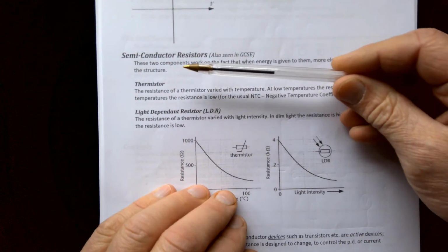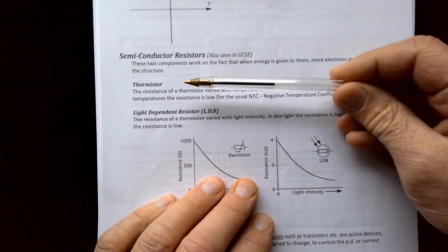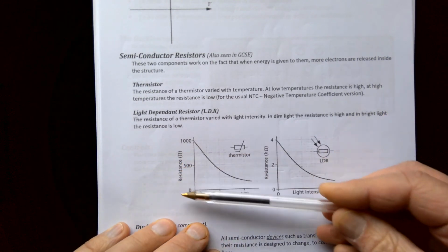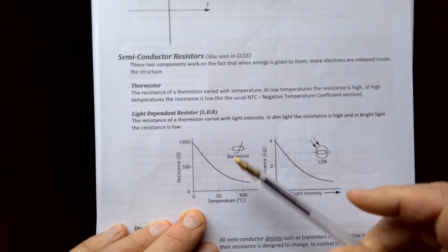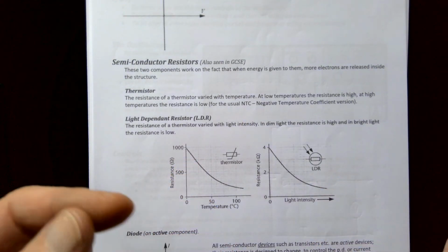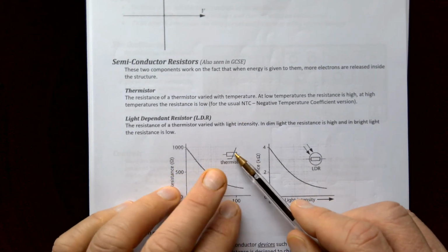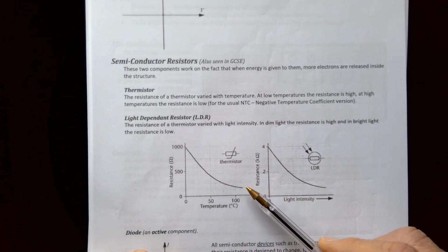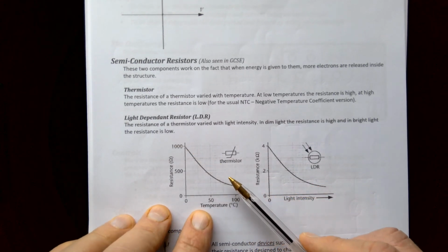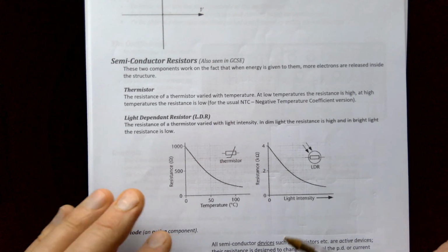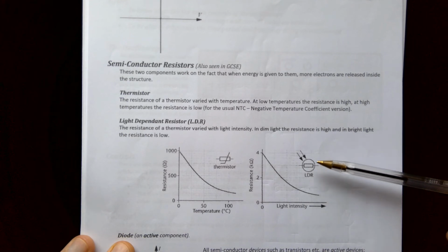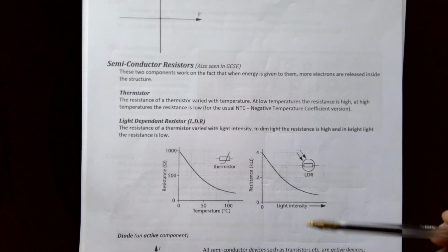So we can have a passive device again that works on semiconductors rather than metals. So that's a thermistor, and that's fairly typical. You can get two types, but the ones that are the simplest, the ones that work just on being a semiconductor, are usually negative temperature coefficient. So I've put it here for you. The resistance will go down as the temperature goes up, but I'm going to get you to find out the voltage current characteristics because that's important. LDRs, light dependent resistors, again it's a semiconductor, fairly passive, slightly more advanced in terms of its construction.